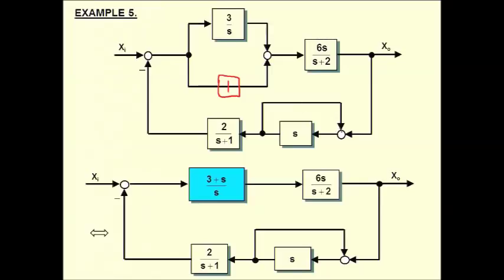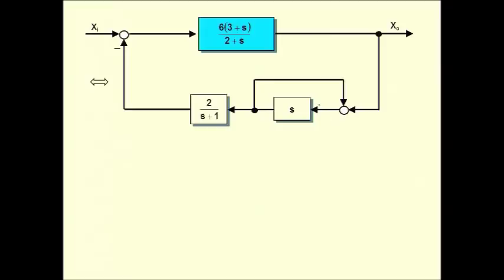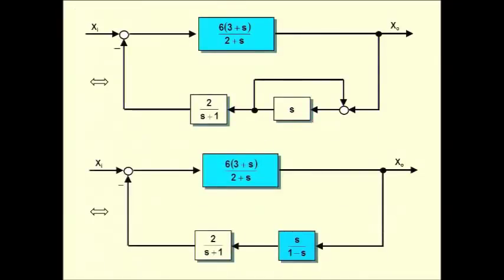And then the other thing is this guy here, which looks a bit backwards because you go, hang on, I'm used to seeing something like this out the front, like this one is here. I'm used to seeing a summing junction and then feedback, and this is a summing junction and feedback this way. It seems a bit backwards, but don't get fooled. All you have to remember is that between here and here you have a simple feedback where the feedback transfer function is 1, and you just combine these two together using G over 1 minus GH, because it's positive feedback. So that's what I'm doing at this step here.